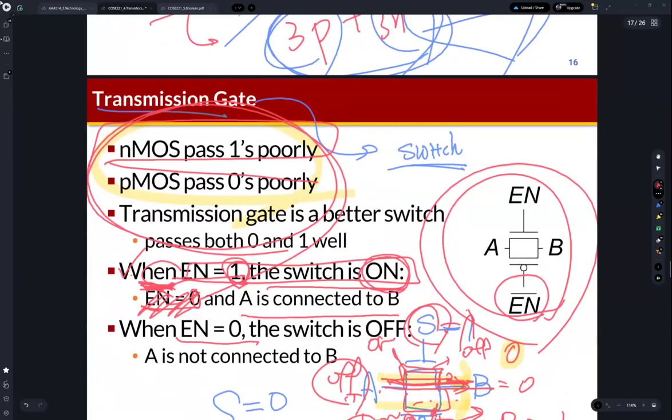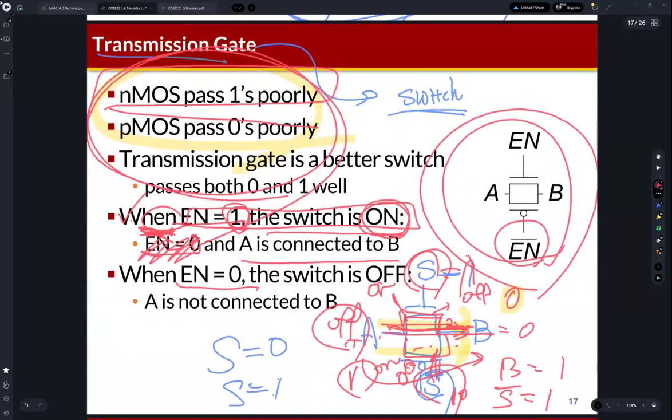Okay, like this. And then I also explained the transmission gate. So this is the switch. Actually, it's a true switch, but we need to combine the NMOS transistor and the PMOS transistor for implementing a good switch. This is because of this property, right?